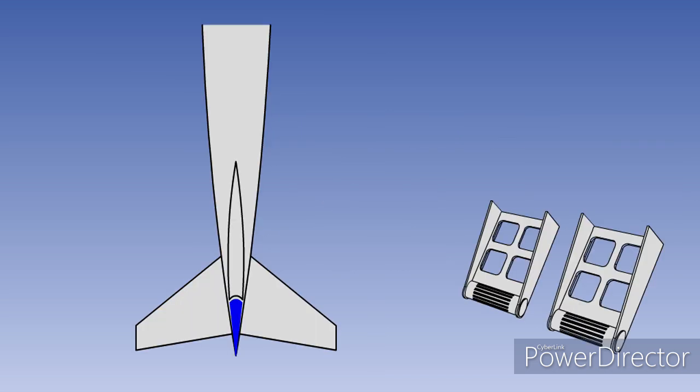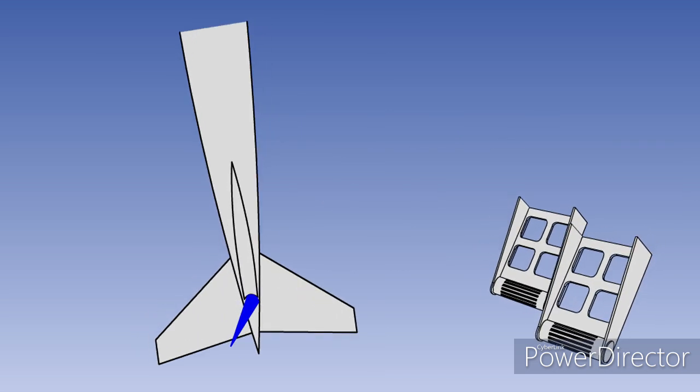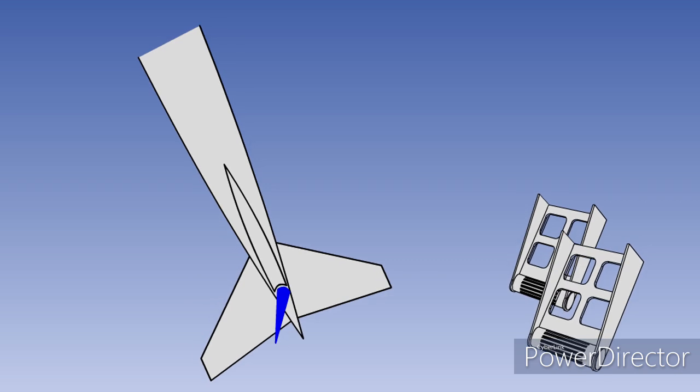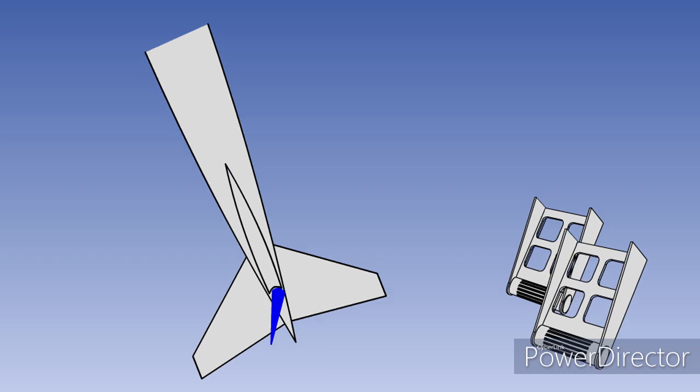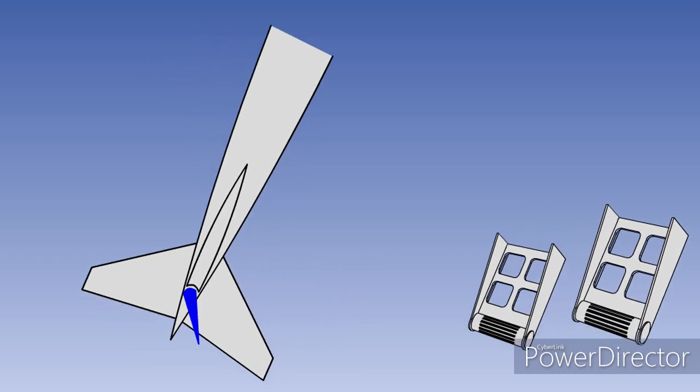Rotation around the normal axis is yawing and is controlled by the rudder, which is normally fitted to the trailing edge of the tail fin. The rudder is required to maintain directional control with asymmetric power, to correct for crosswinds on takeoff and landing, to correct for adverse yaw, to recover from a spin, and, on a single-engine aircraft, to correct for changes in propeller torque.